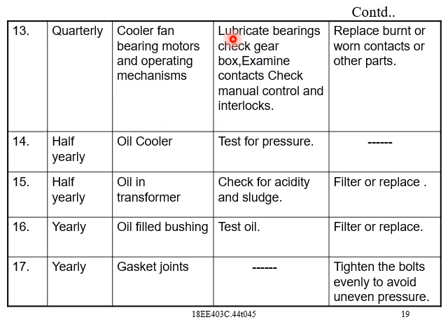Already we have seen, and it should be inspected for lubricate bearing, check gearbox, examine contacts, check manual control and interlocks. If any unsatisfactory condition is observed, just replace burnt or worn contacts or other parts. Already we have seen this, the same thing, in the 18th slide.